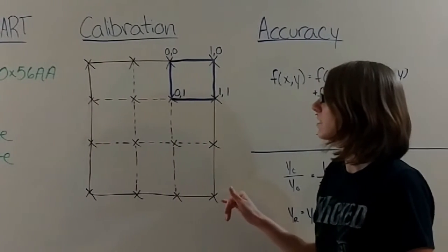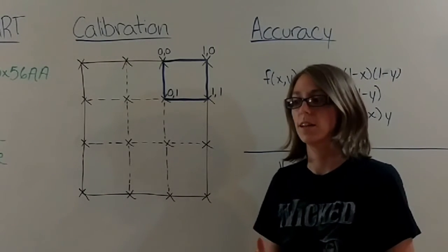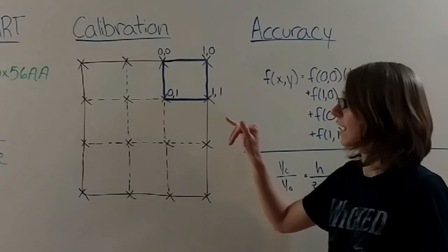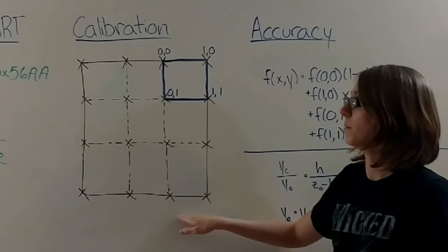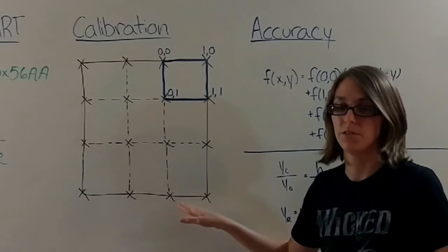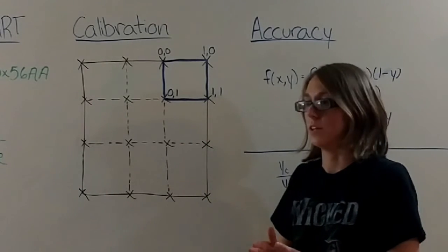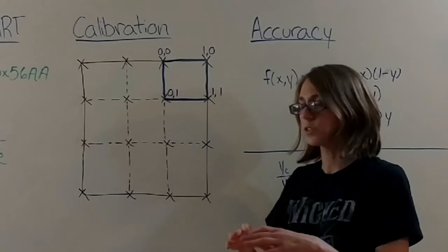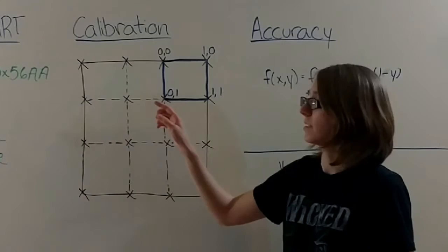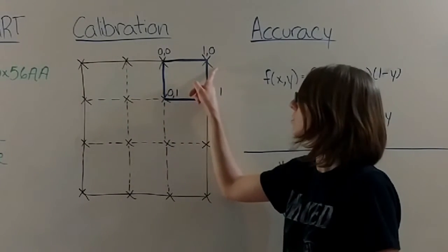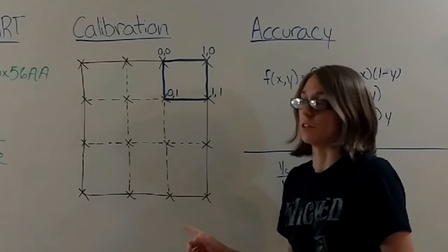Next, I added calibration points to the board, which are the orange objects. The way that I set it up is I use 16 total calibration points, and I read them in directly whenever the program starts, and store them into an array and sort it based on the location here. So it basically stores it in the array from this corner to this corner and then goes to the next row, using actually a quick sort function.